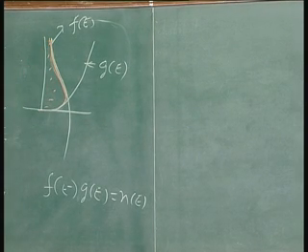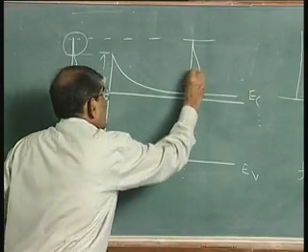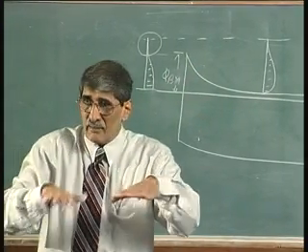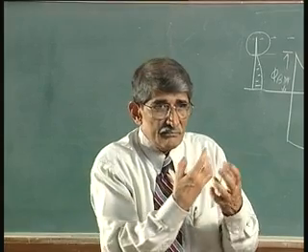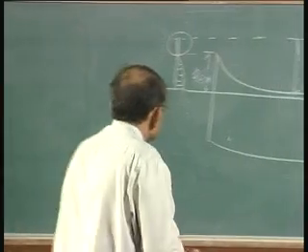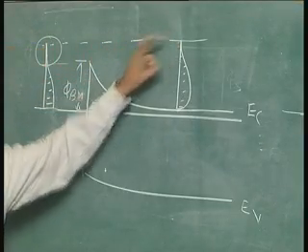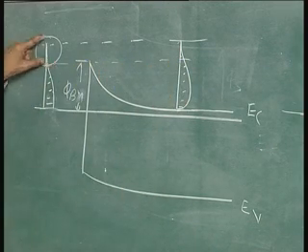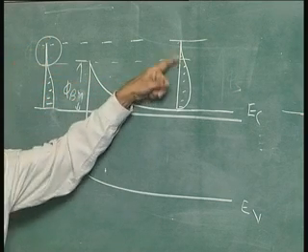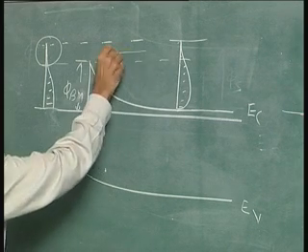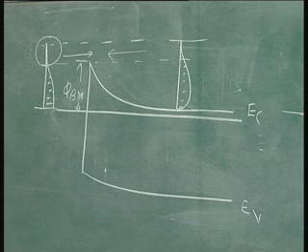Now, that is what I put here. So, you have electrons like that. Now, you can see the Fermi level has adjusted itself ultimately by transferring electrons from the semiconductor to the metal in thermal equilibrium, such that the distribution tip here and the distribution tip there almost match. This would mean that under thermal equilibrium conditions, if you integrate the number of electrons above that and the number of electrons above that, they should be the same, because these electrons can cross this way and they can cross this way. The number crossing from metal to semiconductor will be equal to the number crossing from semiconductor to metal.